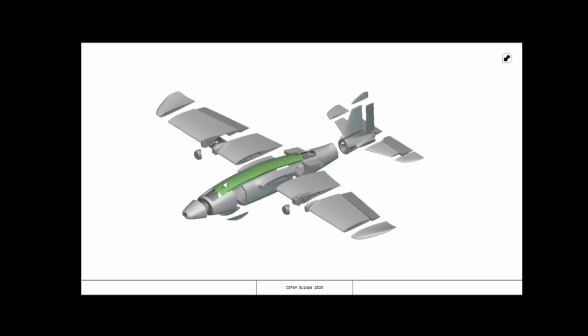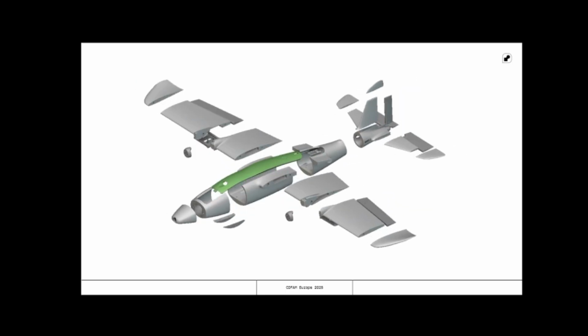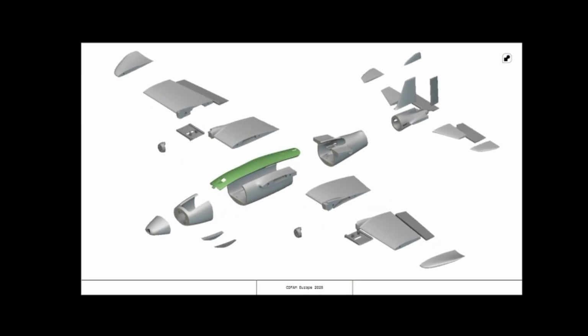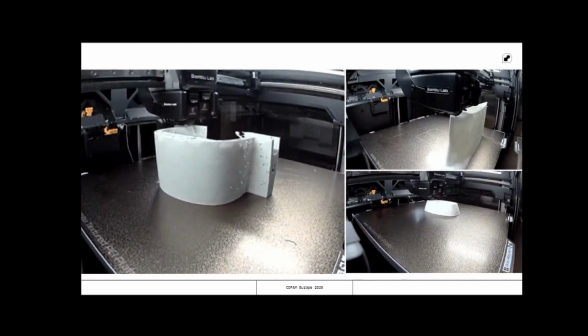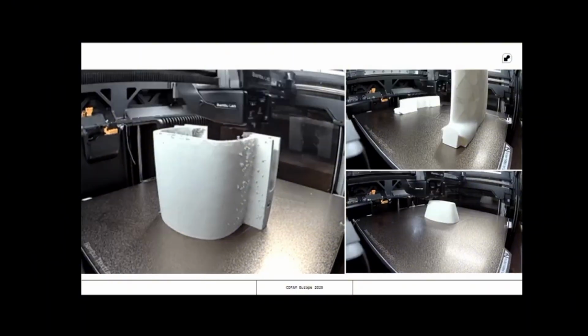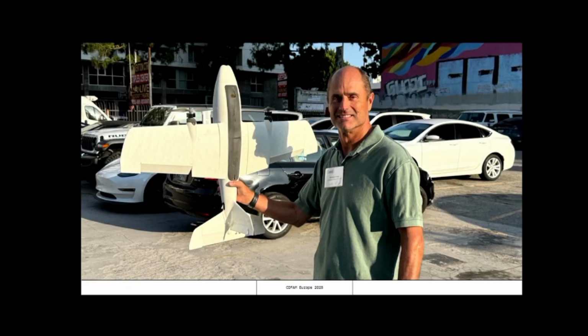This is made from about 23 different unique parts that come together. This is the airframe. There's obviously motors and electronics that go into this as well. You can see all the different parts. If you are interested in the assembly instructions for this, my friend in New York has a company that you should look into called Dirac. That's Phil Ehrenstein. It's really interesting. Each of these components is optimized to be printed with no support structure, and you push a button, and if you have a couple of cheap FDM machines, you can print all those different components. And here we have George Irving holding his first version of this aircraft, which is awesome.